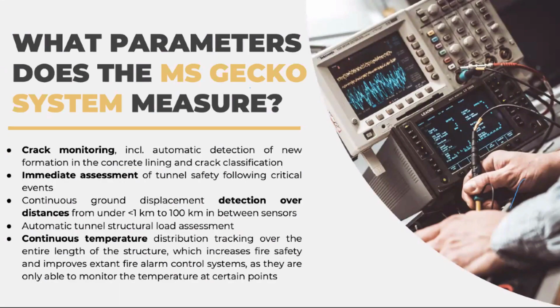Yes, so this is something we already talked about. Crack monitoring is very important, so that we can prognose which cracks need to be classified as requiring immediate actions, or some damages that might not require immediate actions but can be put in the next maintenance schedule. Continuous ground movement and displacement monitoring is also very important, and we can do this monitoring over a long distance.